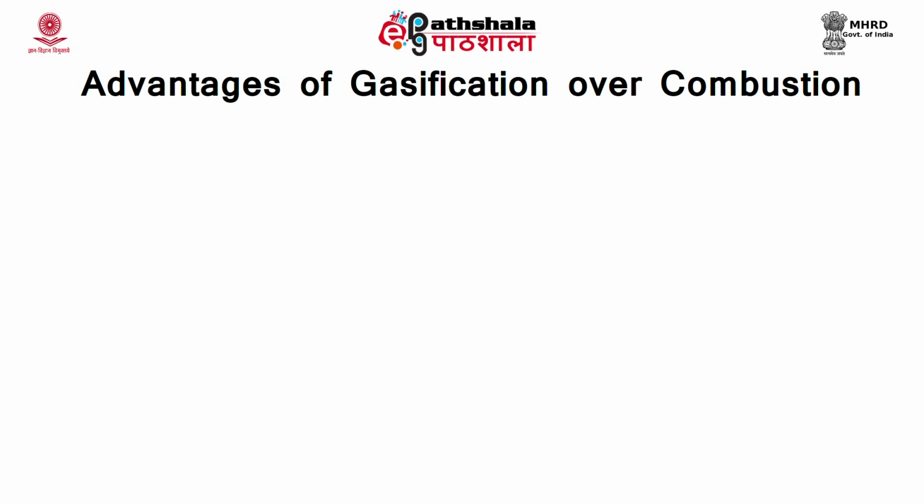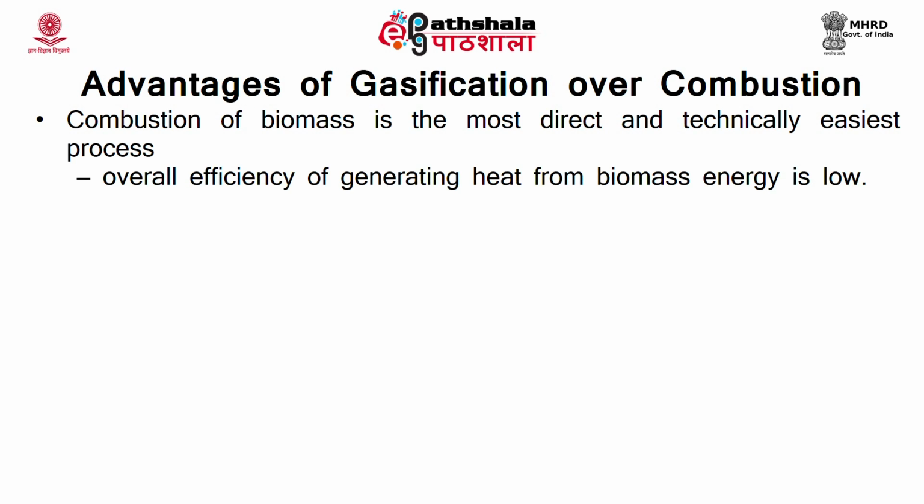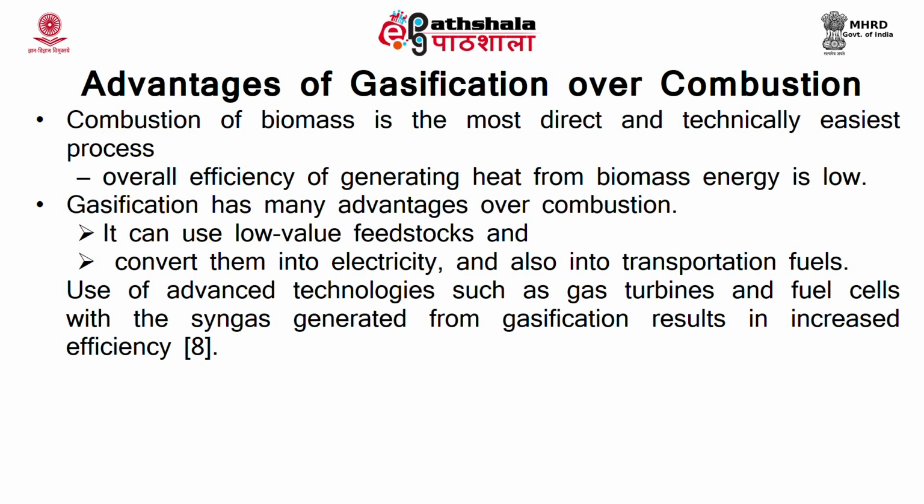Let us see what are the advantages of gasification over combustion. Combustion of biomass is a direct and easiest process, and here the overall efficiency of generating heat from biomass energy is low. Here complete combustion, or you can say the sufficient or excess oxygen, is used up. Gasification uses low value feedstocks and converts them into electricity and also into transportation fuel, in comparison to the heat energy from the combustion. The use of advanced technology such as gas turbines and fuel cells with syngas generated from this gasification also increases its efficiency over the product of combustion.